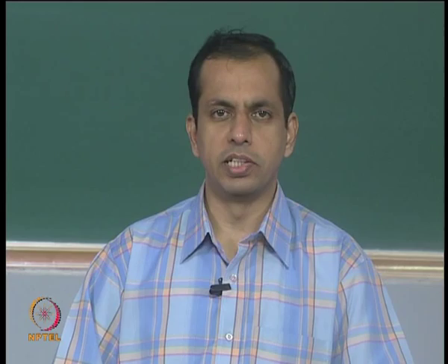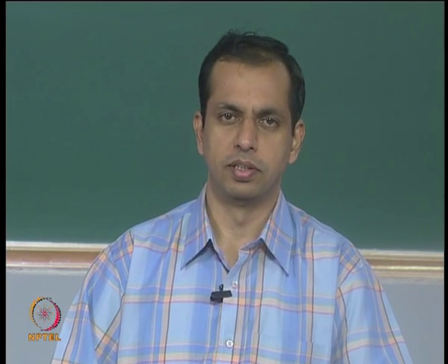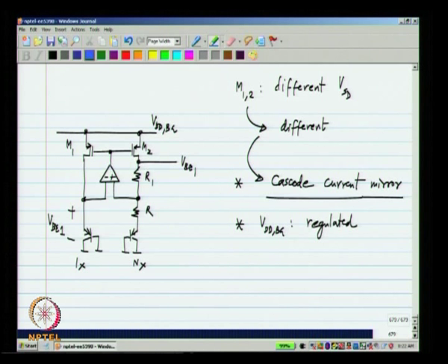It is when you put the channel length modulation effects in the current mirror M1 and M2 that you see some effects. So, even if that VDD BG, which is the supply for this cell, is crudely regulated, that should be good enough. So, both techniques are used. Sometimes you use cascode, sometimes you use the regulation, and of course, you can use the combination if you wish. So, this would be made cascode.